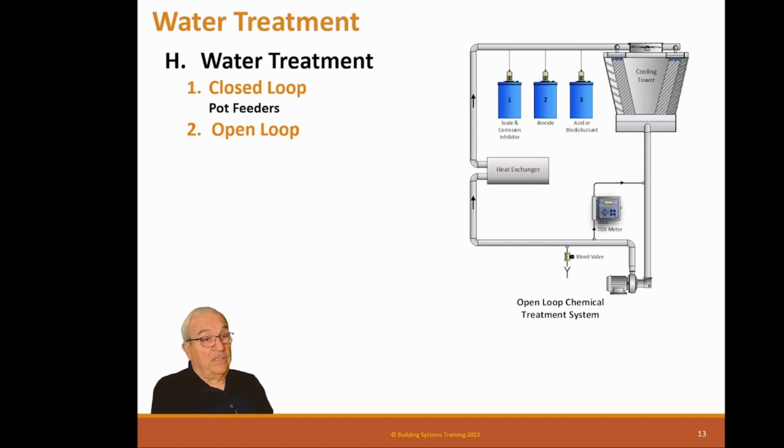Because what happens inside the tower, it's normally really alkaline. And it gets too alkaline and starts scaling. So we want to pull that alkaline level back to where it's not corrosive. We want to keep the pH right around 5 to 6. We want to keep it right in that range. And then that scaling chemistry actually tries to protect the tower from corrosion.